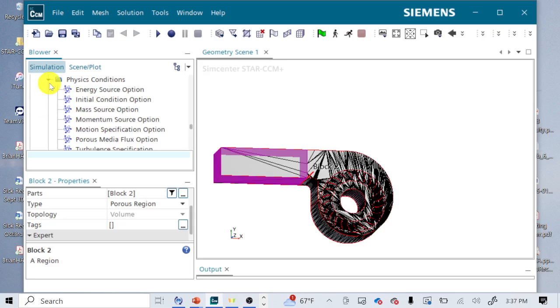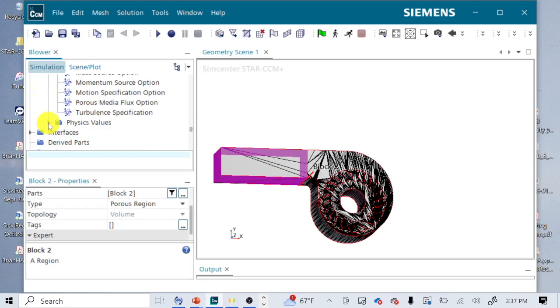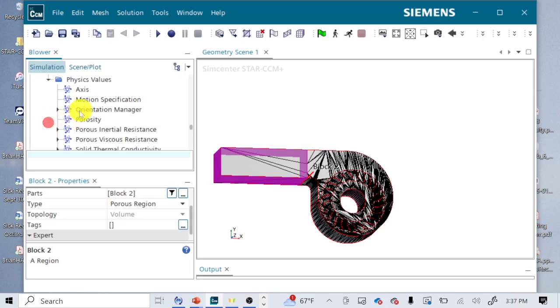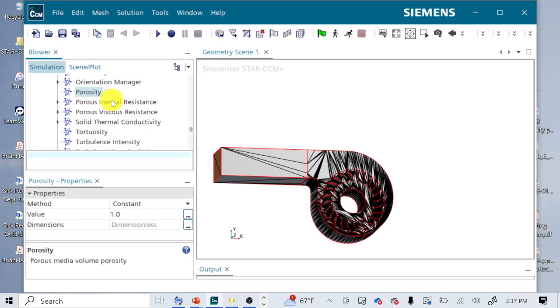It's a porous region, which again, the idea of a porous region is that it simulates something like a close packed surface, like a sponge or closely packed fins, or something that provides resistance to the flow. If you have a denser set of fins, it provides more resistance. If you have fewer fins, it provides little to no resistance. Without changing literally anything, we can arbitrarily make this box, without changing its size, as high resistance or low resistance as we want.